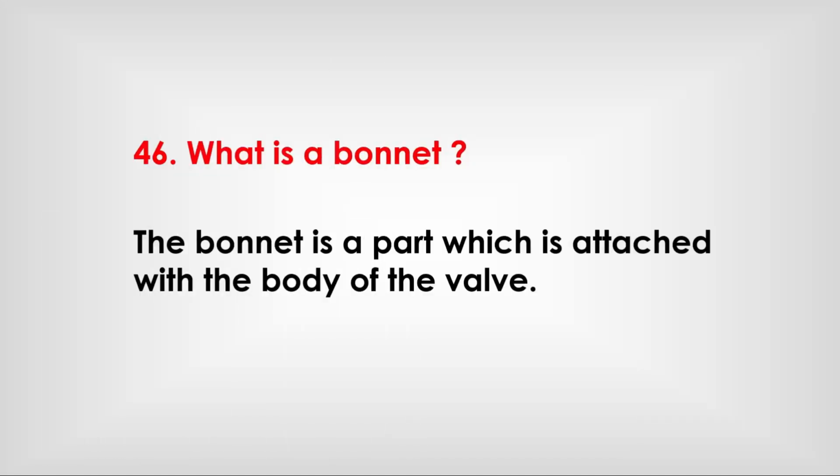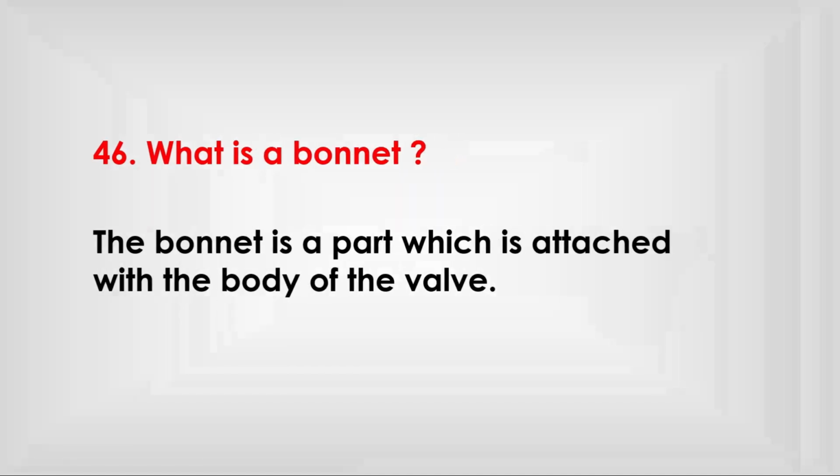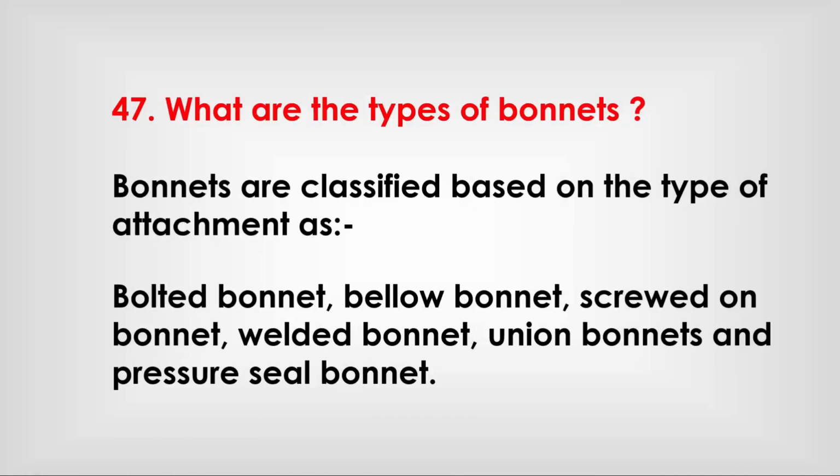What is a bonnet? The bonnet is a cover which is attached to the body of the valve. What are the types of bonnets? Bonnets are classified based on type of attachment as bolted bonnet, bellows bonnet, screwed bonnet, welded bonnet, union bonnet and pressure seal bonnet.